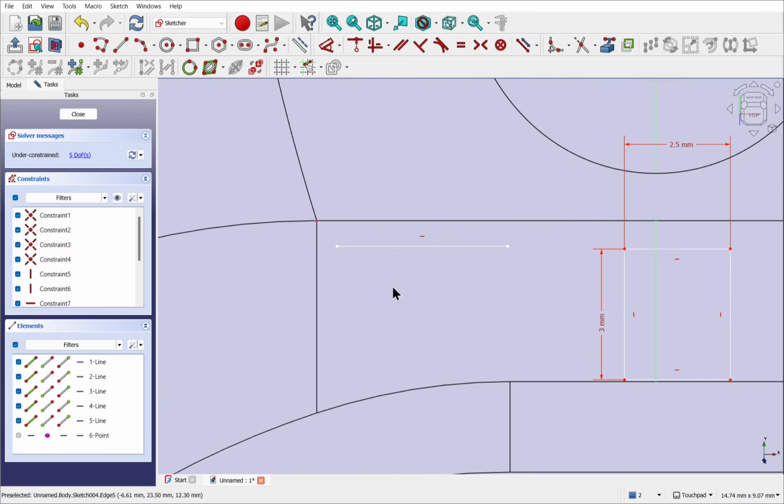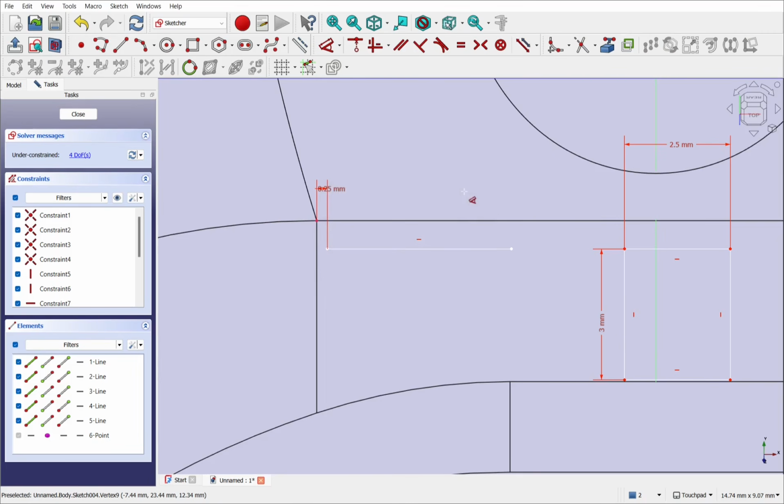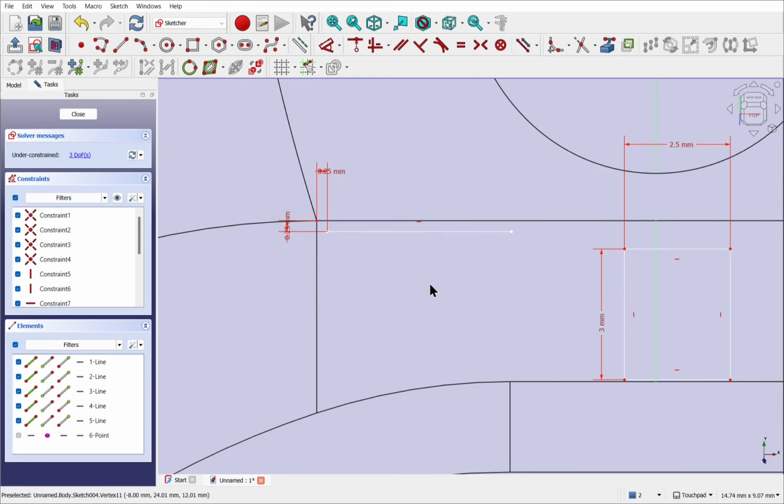We're concentrating on our construction geometry at the moment. So at this point on this one, set some dimensions. Go for length first of 0.25 and some height of the same, 0.25. Right click to cancel the tool and move this across.